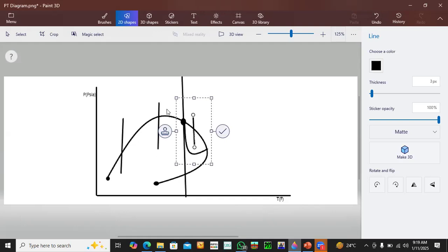Also, there is volatile oil, which is not far away from the critical point, or closer to the critical point, though some literatures will discretize this into five types within the oil reservoir region. You might say far critical, black oil, then volatile oil, then near critical. Some of them will say low shrinkage, but I believe low shrinkage, near critical, and volatile can fall within the volatile context, and the far critical or low shrinkage oil can fall within the black oil. So it all depends on the literature you refer to.